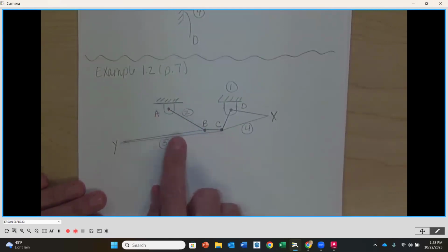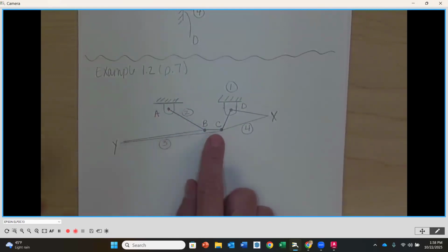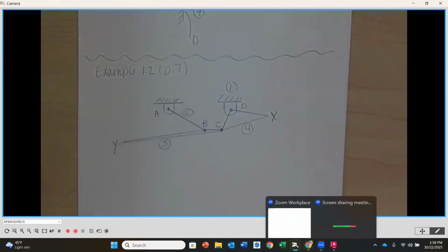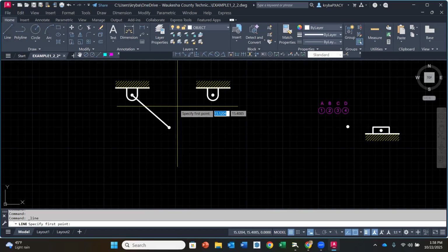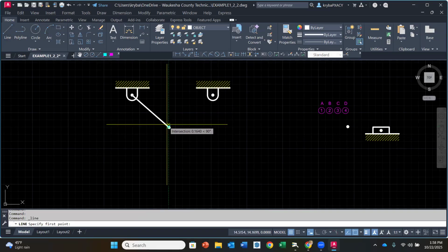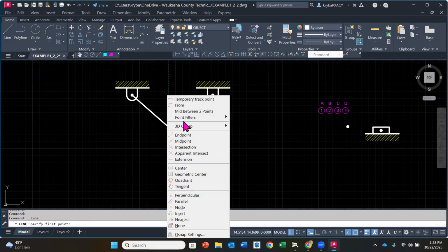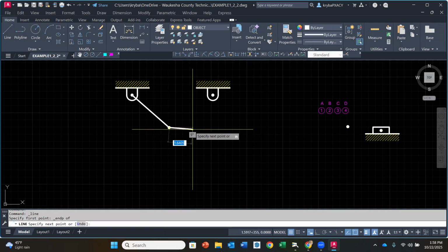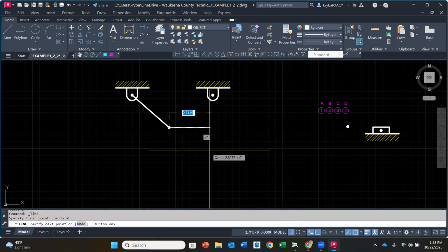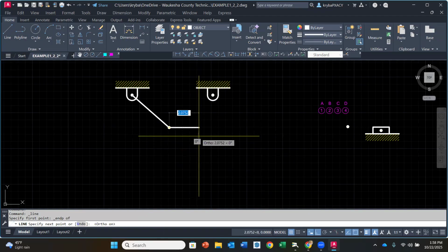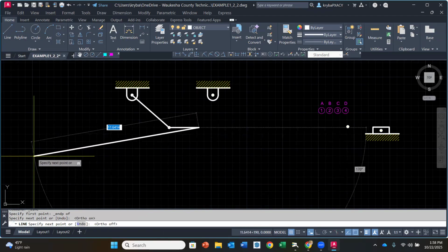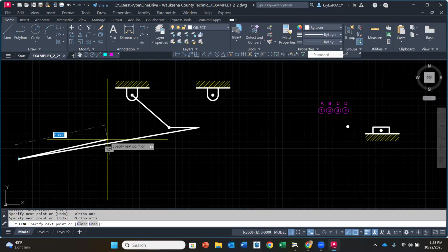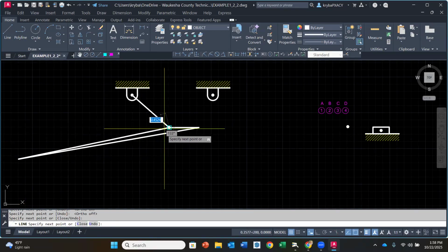Now I'm going to create my handle. Again, eyeballing, I'm going to do a line from the endpoint. I'm going to go horizontal-ish, turning ortho back on and then back off, and then go out over here and then back up here.